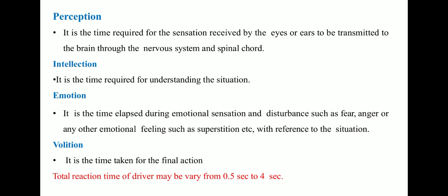And volition is the time taken for the final action. So after any incident takes place, all of this happens inside the human brain to perceive and react, and it is known as the PIEV theory. This is also very important from your examination point of view.